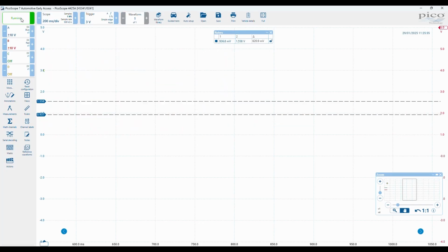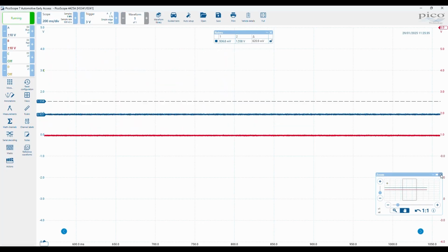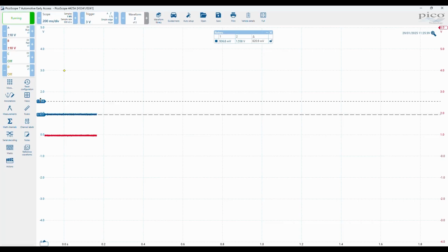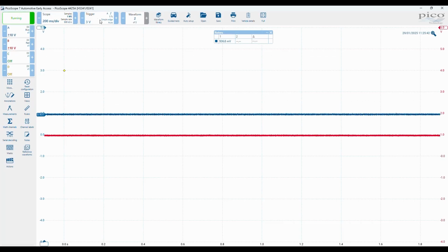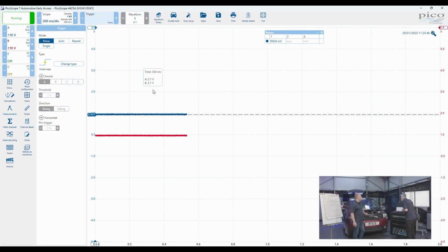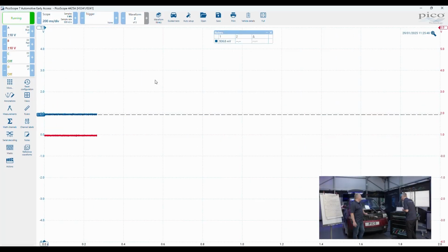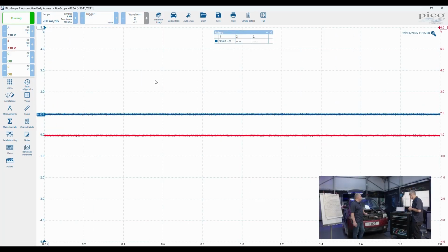Okay. We'll run PicoScope again. I'll take away that ruler. We'll take away the trigger. The trigger is no real help at this point. And how long is this going to take now for this to actually drop down to 0 volts? That's really what we want to see, because anything that's holding the bus level at that voltage has a potential to give us parasitic drain.